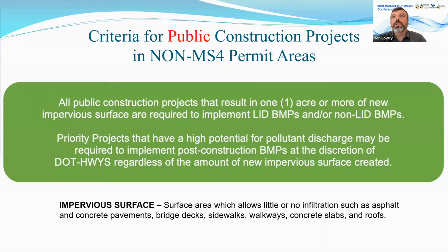So, criteria for public construction projects in non-MS4 areas. Now we're talking about Big Island and Kauai, areas that don't have an MS4 NPDES permit. And for the most part, you can just go back to the previous manual, and we haven't changed much of what the requirements are from the previous. The previous manual didn't distinguish between MS4 and non-MS4 permit areas, but the new manual does.